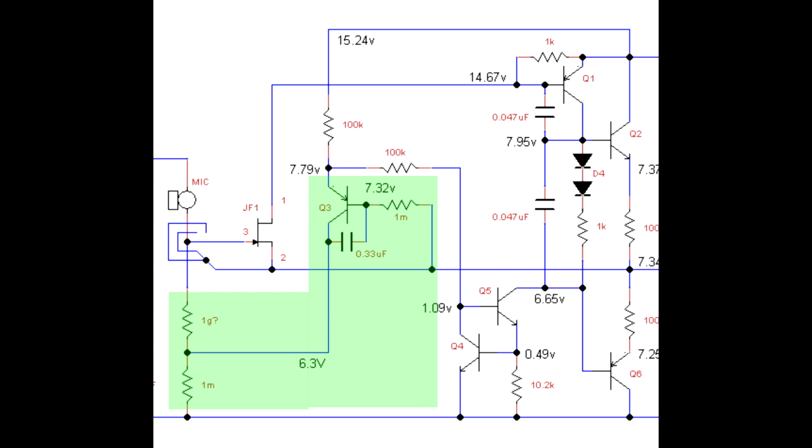And that center wire, this output signal, is going up and down with the audio, and that is buffered through this transistor and sent down to that 1 gig ohm resistor. So the DC bias point of the bottom of that 1 gig ohm resistor is not ground, it's elevated to a higher voltage, and it's also moved up and down with the signal to reduce any capacitance effects of the JFET transistor.